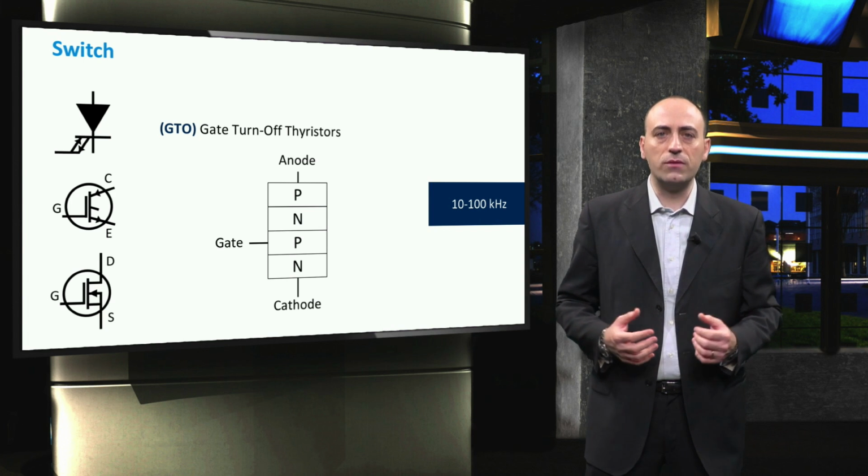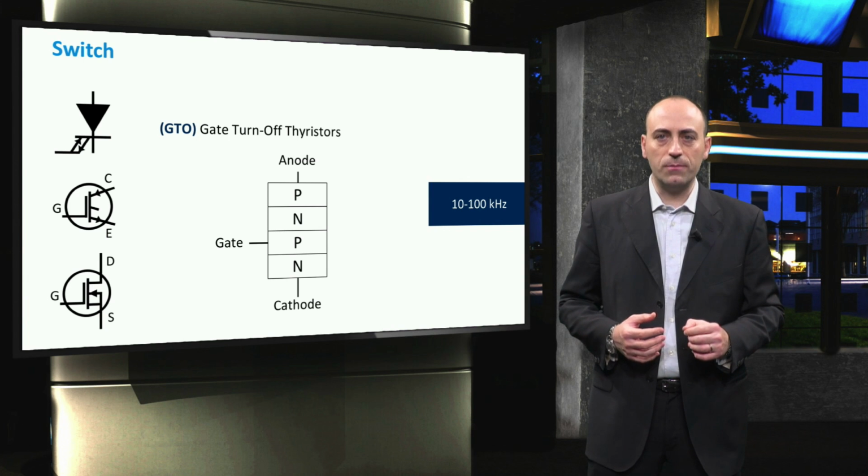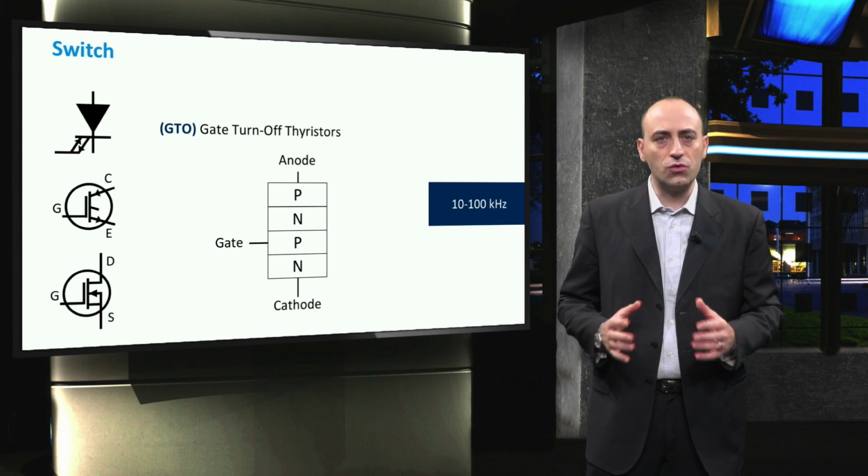One disadvantage of these components is that thyristors cannot be turned off, but only turned on by applying a signal to the gate. Such switches lead then to a very high harmonic content, requiring additional filters in order to make the output compatible with the electrical grid. A special type of thyristors used nowadays are the gate turn-off thyristors, which are fully controllable because they can be turned on and off at will. Thyristors are only used for inverters with a power of 100 kilowatts and above.